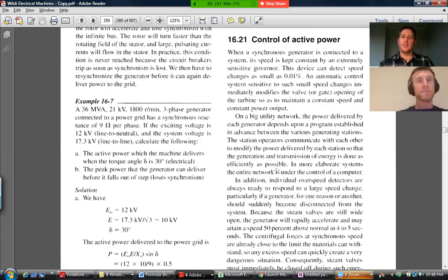Okay. So yeah, there's another whole story as to how to load shed, etc., to try and keep everything balanced, or allow more steam into your turbines to try and handle that extra power. But eventually everything reaches a maximum operating point, and you can't keep pushing it too far. Eventually you reach a pressure or whatever that the thing's not designed to handle, and something has to give. And normally that something is dropping some poor load off the grid unsuspectingly for a time at least, until things come back into equilibrium, and then we can switch them back in.